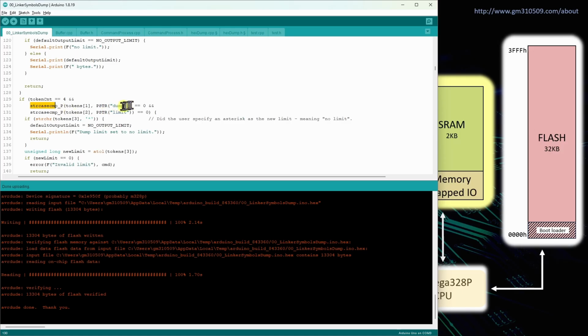I just left these things in the RAM, and so that's maybe not such a good idea, as we've discussed in this video. So I can say, well, leave it in the flash memory or the program memory, which is this red one over here, by using PSTR. So that means mark this dump string as something that just gets left over in flash and not moved to RAM.